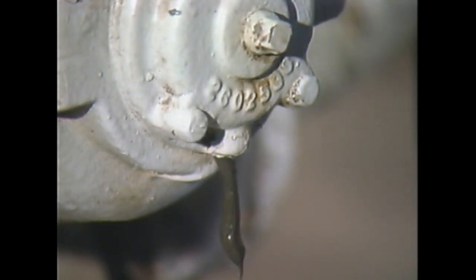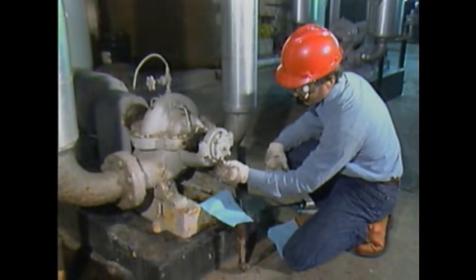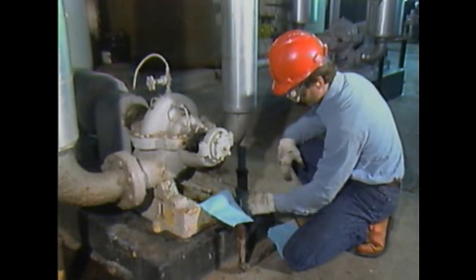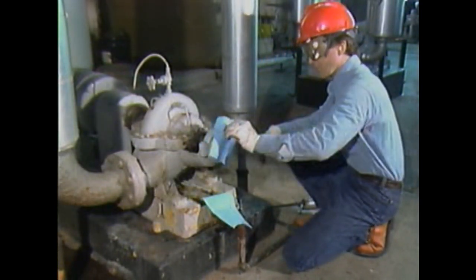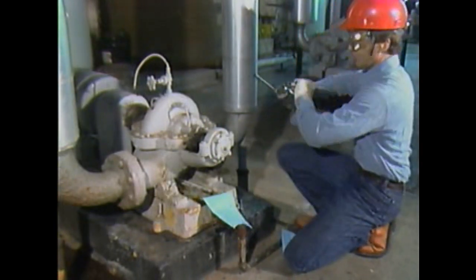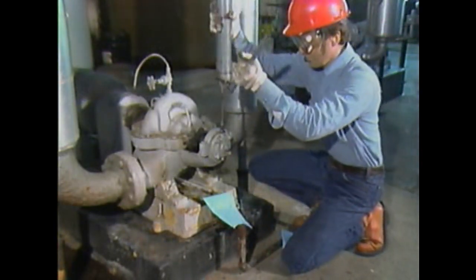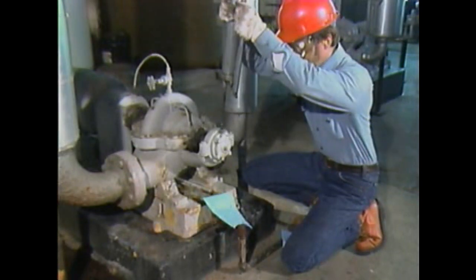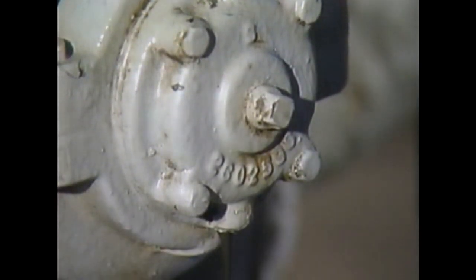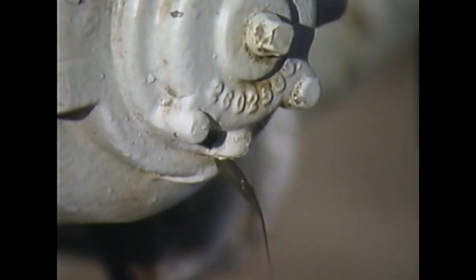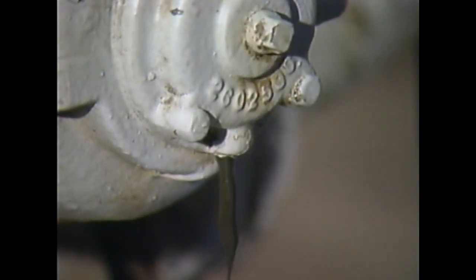In this example, the housing has a drain hole. To prepare to grease the bearing, remove the plug from the drain hole and wipe the grease fitting clean. Then connect the grease gun to the fitting and slowly add the specified amount of new grease while the machine is running. Don't overgrease the bearing. Typically, with a hand-operated grease gun, you should apply no more than 3 shots of grease at a time.